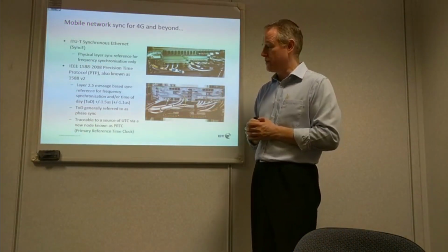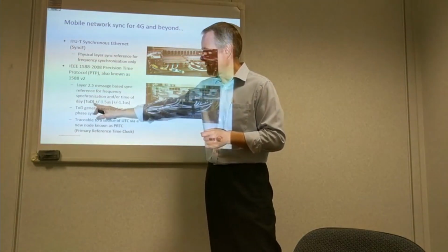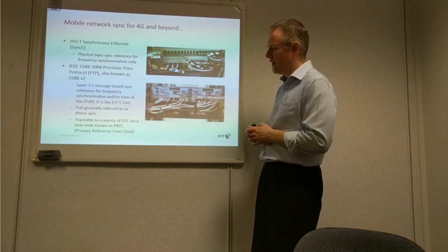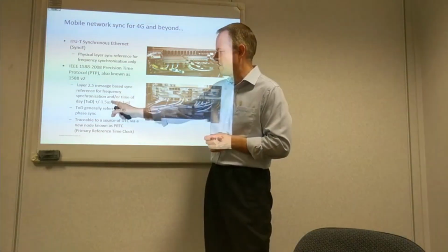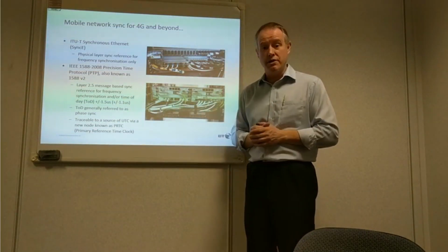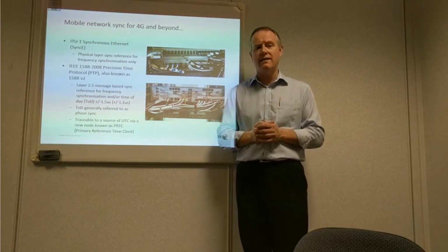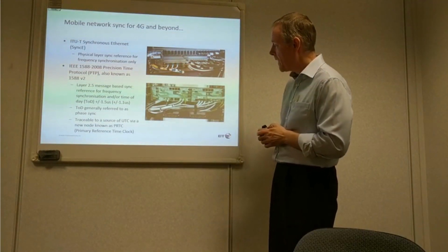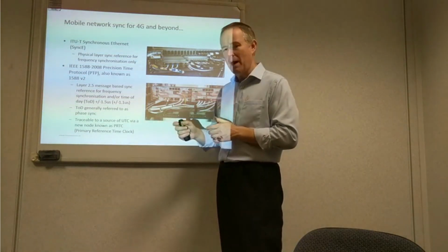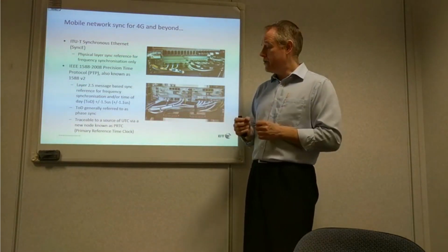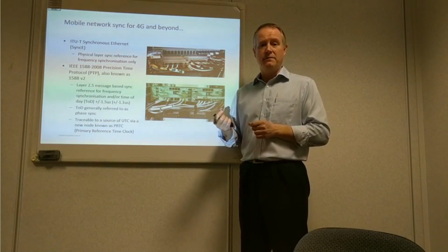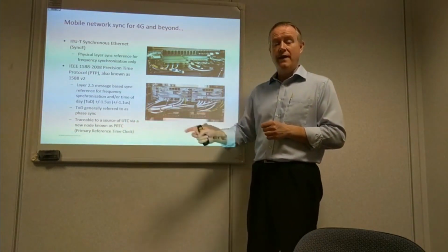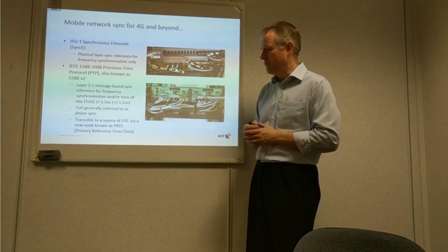converging the two technologies. Now from a phase perspective, we have to deliver plus or minus 1.5 microseconds on the radio interface, which means from a line perspective we're targeting a performance of around about plus or minus 1.1 microseconds. So again, we've got a little bit of budget to play with within the base station itself. And this would now be traceable to some form of UTC typically, so Universal Time Coordinated, so effectively time of day, and that would give us that phase or time synchronization.